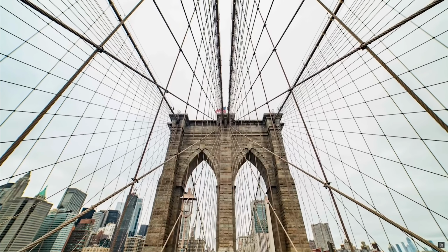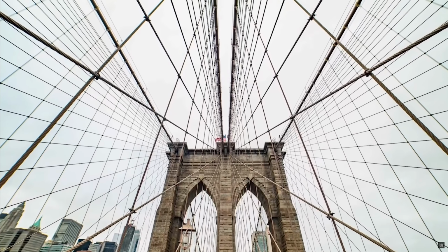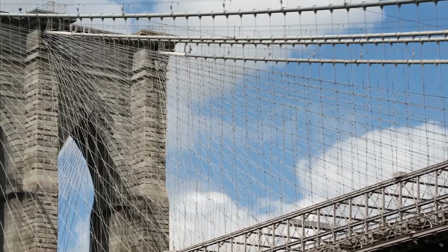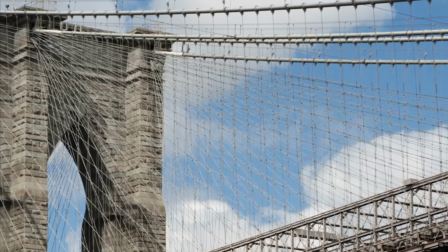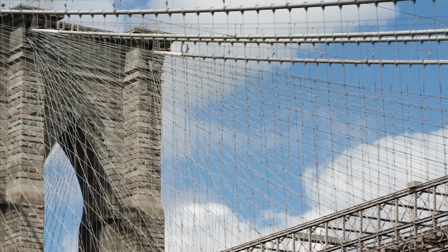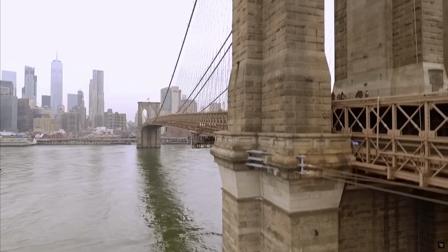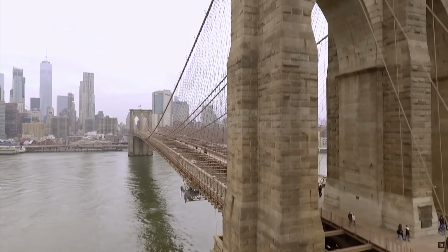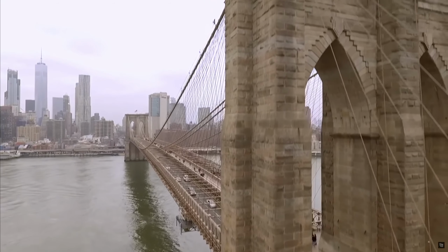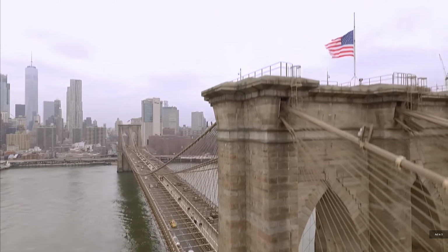The cables of the Brooklyn Bridge are comprised of 19 strands that are then bundled together, and each of these is composed of about 278 wires per strand, and together they actually produce a much stronger tension resistance than if you just had a single solid strand. So those towers on the Brooklyn Bridge are stone towers as well, using limestone, granite, and other rocks that have proven to be able to stand the test of time because of their durability and strength in compression.